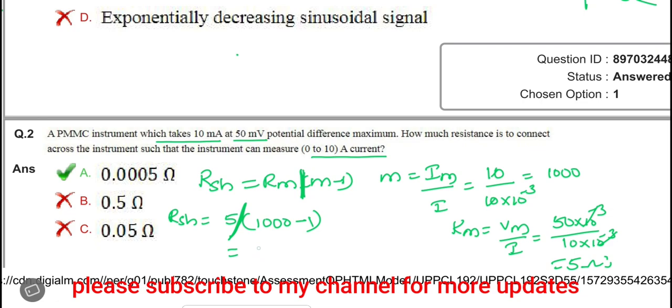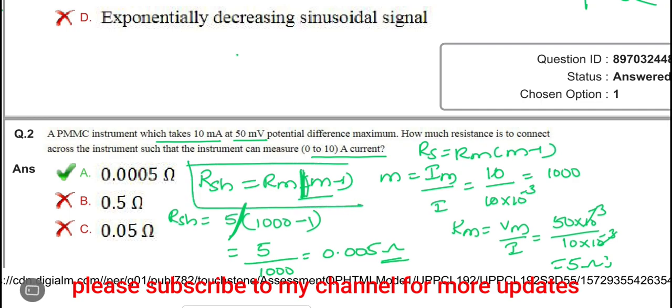Approximately, 5 divided by 1000 is 0.005 ohms. So friends, make a correction here: RS is equal to Rm by M minus 1. For a series resistance, the voltage multiplier is RS equal to Rm into M minus 1. So please make a correction here. The answer is 0.005 ohms.